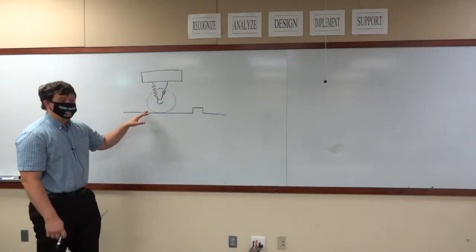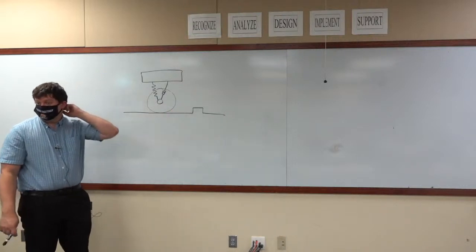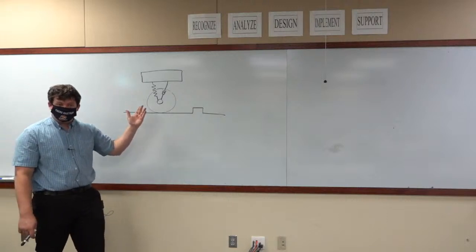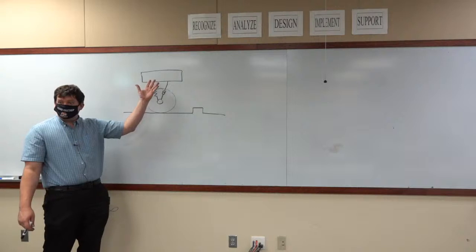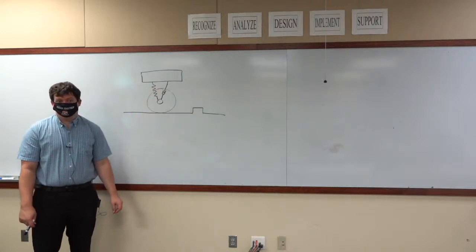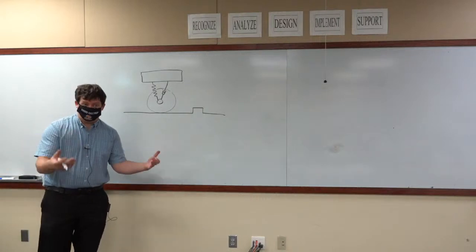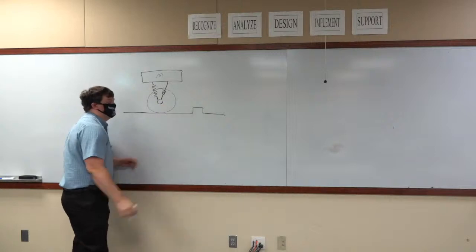Okay? All right, I'm going to take this tire and I'm going to drive it over this bump. Now, the moment that this tire hits that bump, this vehicle is traveling at a fast enough speed that we can assume that the car body does not move, at the very beginning, because this does have a very high inertia.